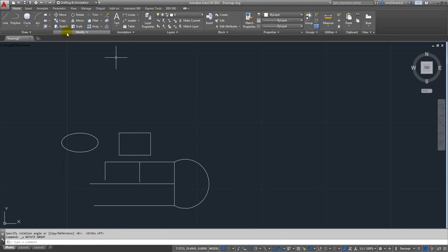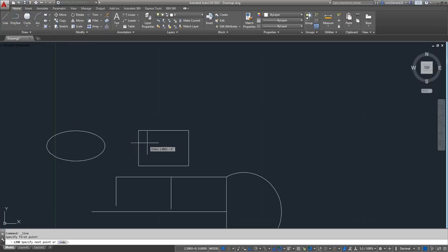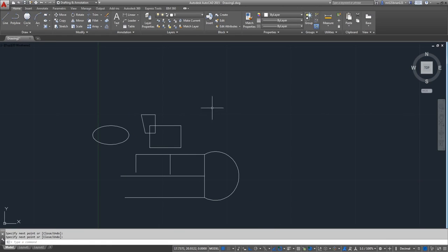Okay, we are going to see mirror. Mirror, for example, we are going to do something like this, and if we press mirror, select the object, we press enter, and then we select, for example, well, we can go right over here, there's the mirror. For mirror I selected the object. First I selected the mirror, selected the object, I press enter, I select where I want to select the objects. Here I had just selected right over here the click, left click, now another click, enter, and that's it.